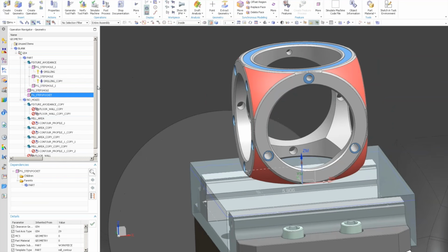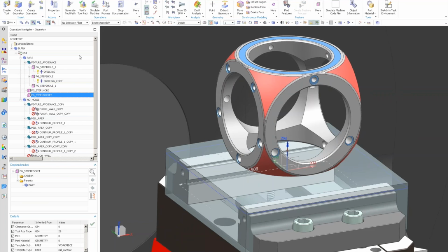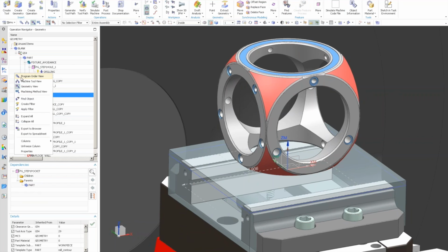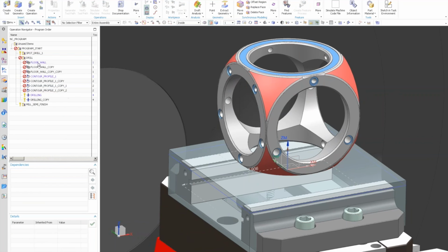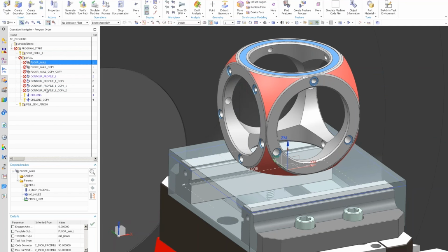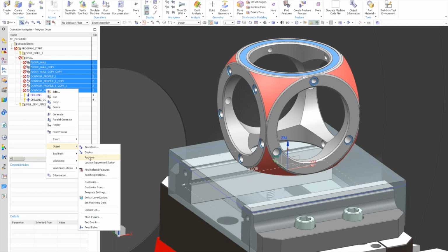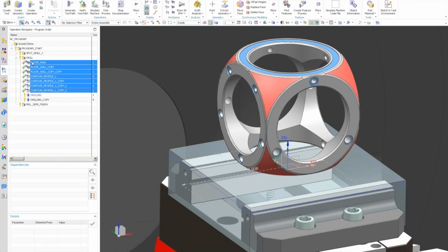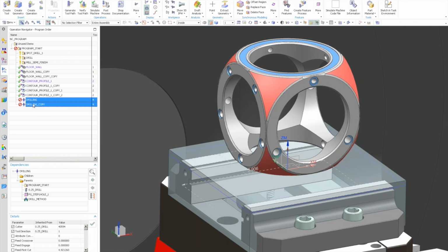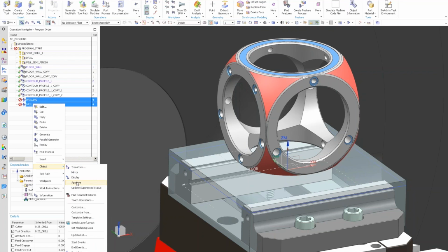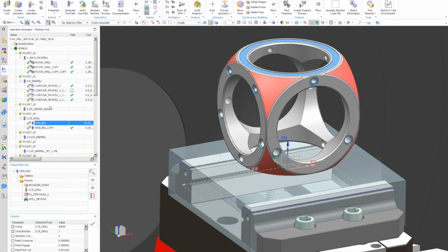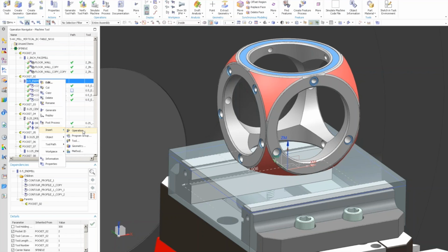All right, so now let's do some roughing and leave some time for questions. So let's create what we call our cavity mill, a pretty good toolpath type for that. So let's find, and I'll just use the 1/2 inch again.